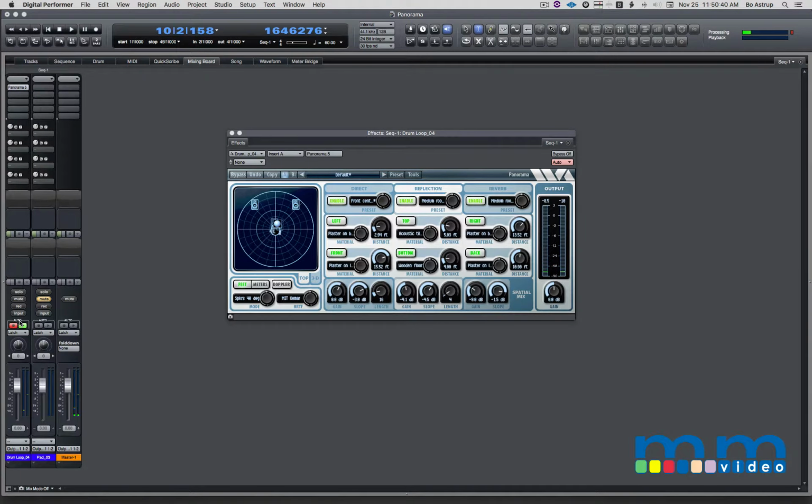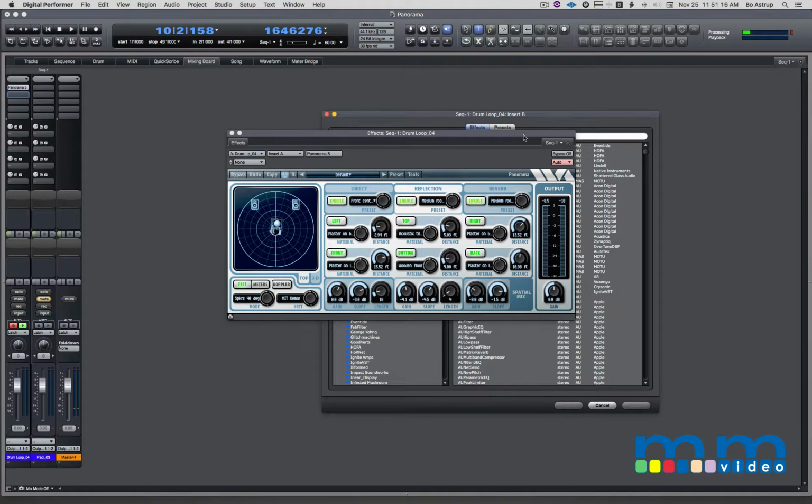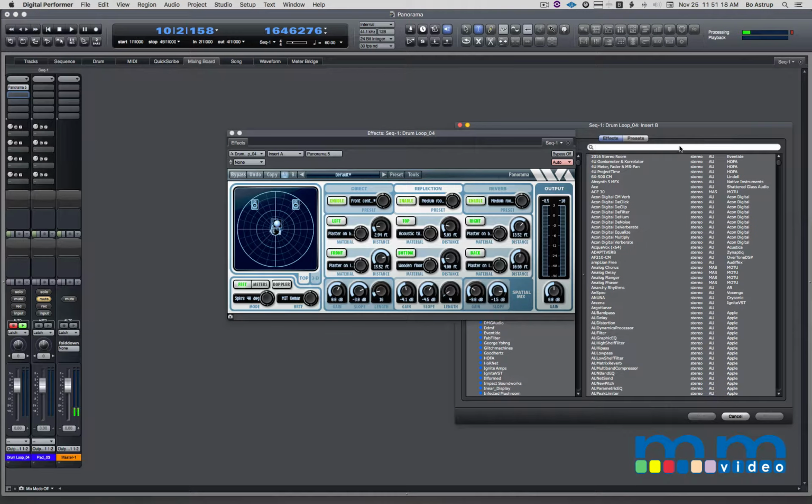Okay, I guess you get the idea here. When I move the sound source around in this room, you will hear phasing from the various reflections, and when I hit dead center, you'll hear a bump in volume because we go mono and it'll raise 3.5 dB. In order to counteract the 3.5 dB raise in volume at the center, I will add a limiter, and in this case, I'm going to use FabFilter Pro L.